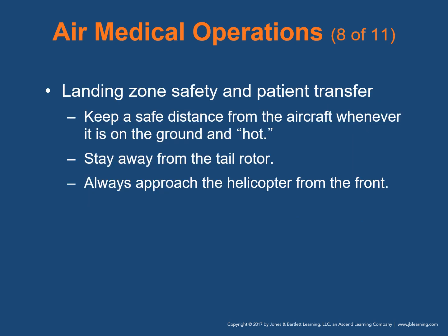Landing zone safety and patient transfer. Make sure to stay away from the helicopter and go only where the pilot or crew member directs you. Keep a safe distance from the aircraft when it's on the ground and hot, which means the helicopter blades are spinning. Stay outside the landing zone perimeter unless directed to come to the aircraft specifically by a member of the flight crew. If you're asked to enter the landing zone, stay away from the tail rotor. The tips of the blades are moving so rapidly they are invisible.